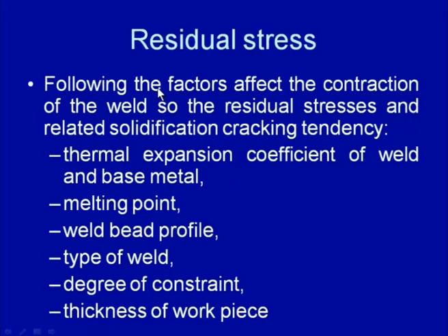The poor properties of the weld metal at high temperature are basically because of the filler material and the weld metal characteristics being used. The differential expansion and contraction of the weld metal is attributed to the development of tensile residual stresses in the weld zone. This kind of cracking is observed mainly along the weld center line due to the setting of tensile residual stresses, especially in aluminum alloys which offer a higher solidification temperature range. We have seen that there are two main factors. One is the setting of the tensile residual stresses, and the second is poor mechanical properties of the weld at high temperature.